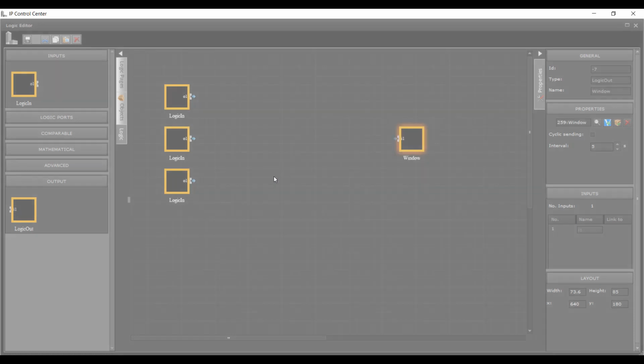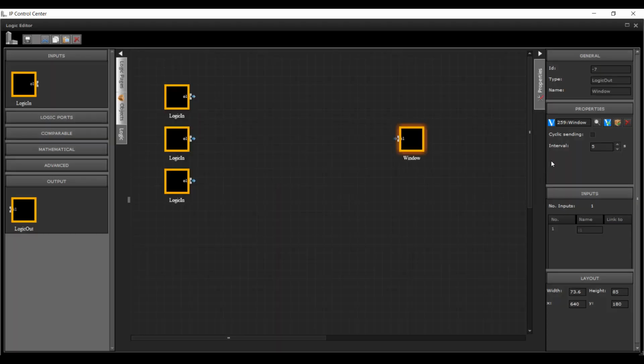All data point types, except date and time, can be used. The name of the assigned object or group address is adopted as the name for the input or output element. When the communication object or group address is changed, the new name is adopted in the element.